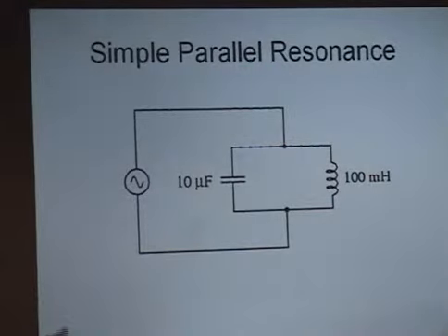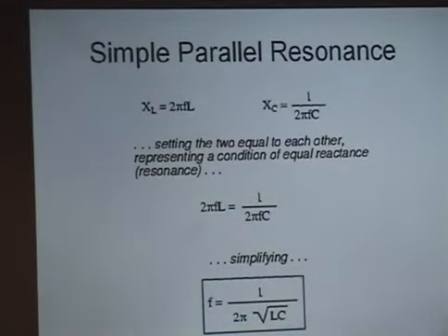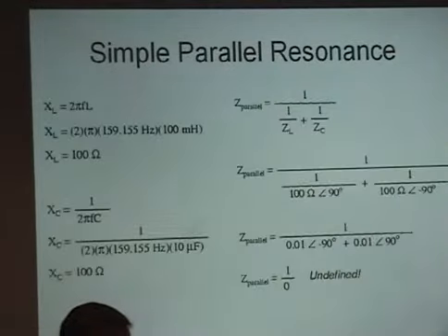If you change that frequency into something like in the 20 meter range or in the 144 megahertz range, then your inductance and capacitance will be very, very different. But you can do that at home. Wayne, you can do this in your head, right? Oh, come on, get out your calculator. You can do that. All you need to do is change the frequency there, and then as long as you work with 100 ohms as reactance, you can work backward and get the right inductance and the right capacitance.